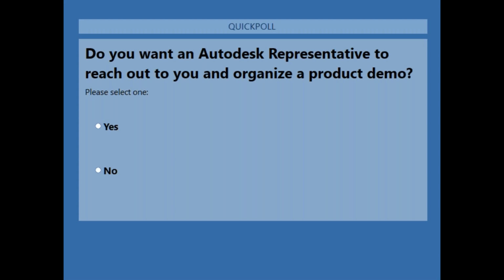One last question talks about how we integrate data coming from Plant 3D to Revit, like schedules and P&ID. To integrate Plant 3D's P&ID with Revit, there is something called a P&ID add-in tool which sits on top of Revit and which could integrate the data coming in the P&ID format from Plant 3D into the P&ID piece in Revit. We already have a lot of information on the knowledge forum. When I present my next webinar, I'll make sure I showcase that particular piece of the workflow of P&ID integration between the two tools.